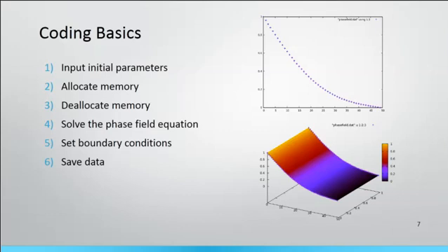You must then code to solve for the phase field equation for 2D heat. This requires inputting the solution that we previously solved for analytically. You then apply the Dirichlet and the Neumann boundary conditions, as we did when we determined the analytical solutions. You can then output the data as a file, which can be plotted using open source software such as GNU Plot, which is what was used here. From a positional profile, the data will look like the graph on the top, while incorporating both time and position will yield the 3D compositional gradient on the bottom.